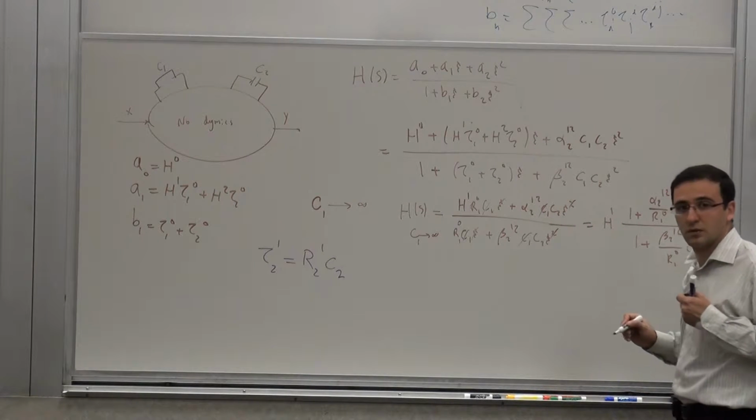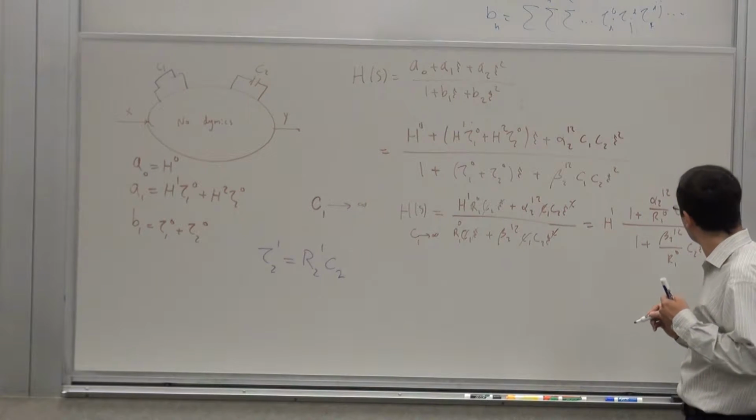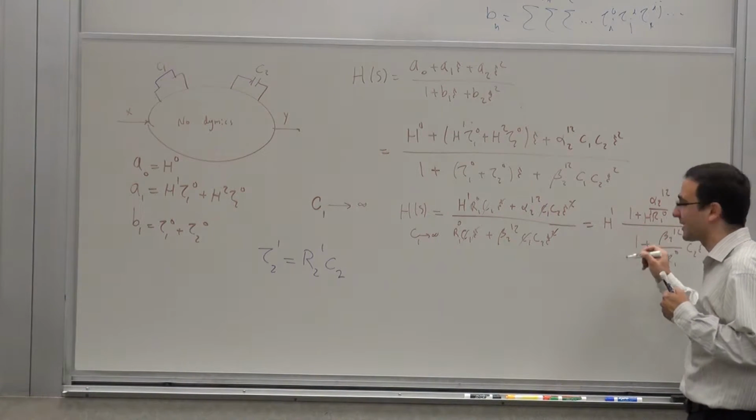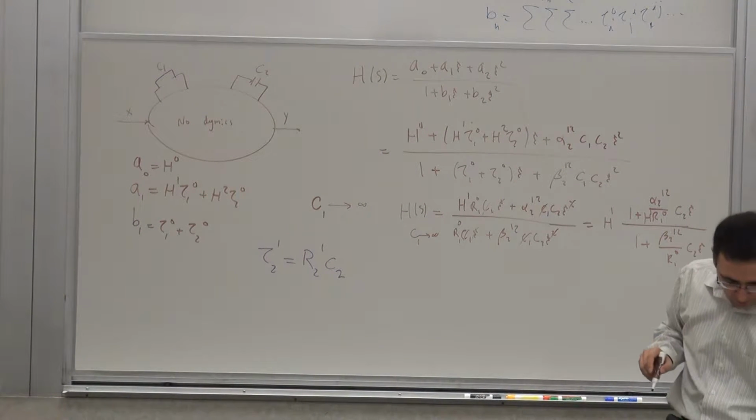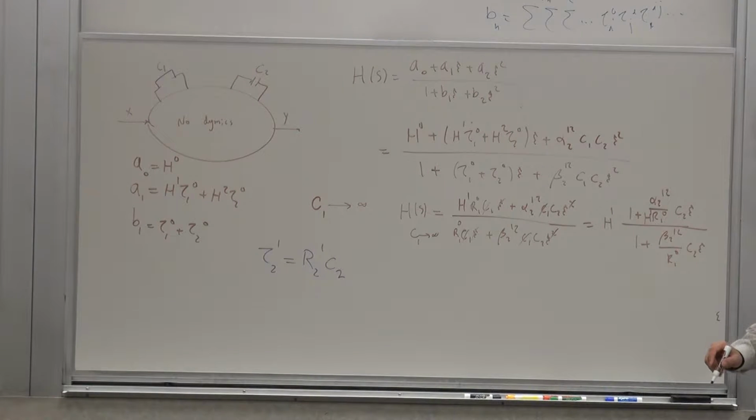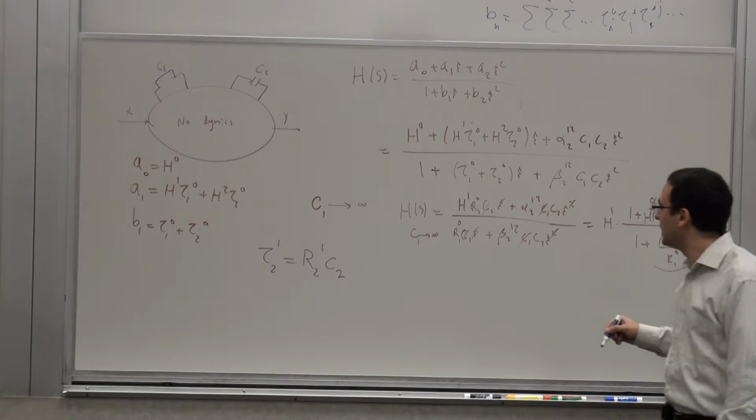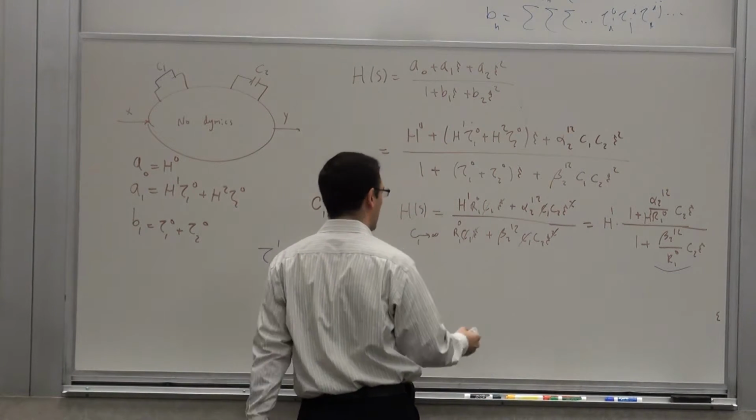There must be H1 in the, yeah, in the second term of the numerator, you have to have H1. Oh, okay. Yeah. Going to factor it out. Yeah, that's right. So basically, that's what I would be left with. Now, but now I know what this term is, right? Because this is the time constant of this new first order system. I've created a different first order system, a new first order system. This is the time constant of the first order system, which has to be equal to that. So I will equate those two.